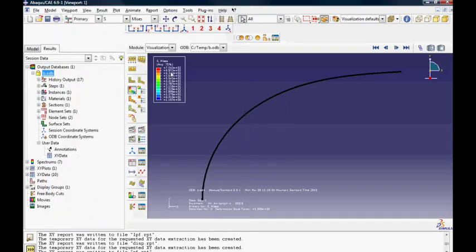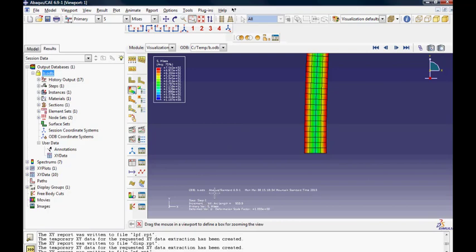You can see that although the structure is unstable, the stresses were right now at about 800 or 760 MPa. The ultimate stress is actually 1200, so material wise it has not reached the ultimate stress yet. The problem is unstable, and any slight increase in the load will lead to collapse.